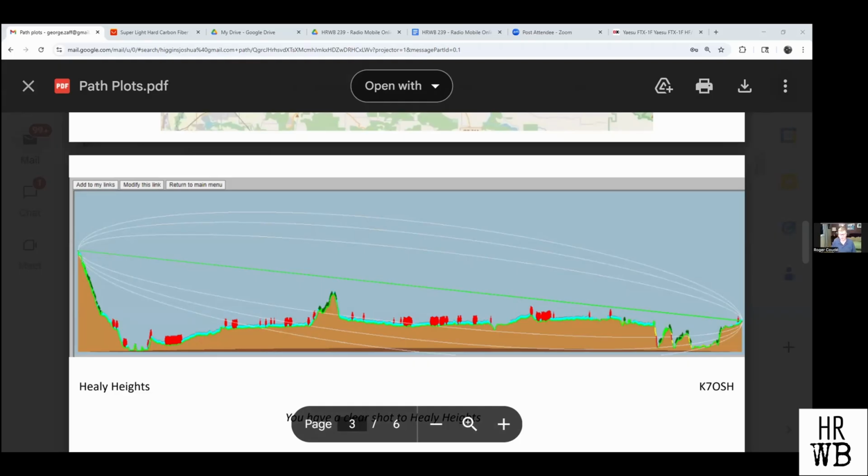So first of all, when we work with a path like that, we work with a two-dimensional plot, okay? In reality, they are three-dimensional. They are, as I said, like a football, okay? But it's a good assumption to use a two-dimensional plot because of the Earth itself. It's a flat Earth that blocks half of the energy. This is what you have here. You have line of sight, but at the limit there is a building in red, at about 80% of the path.